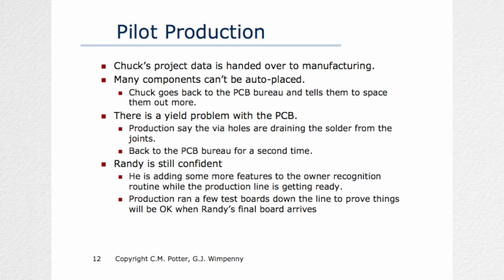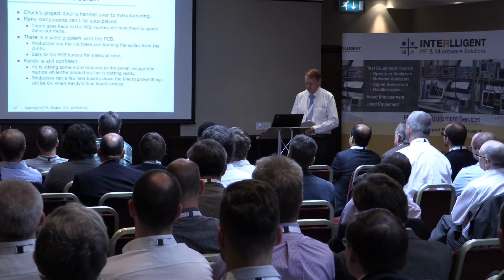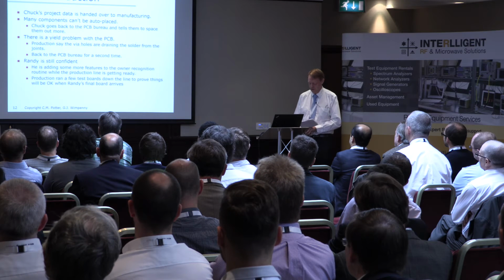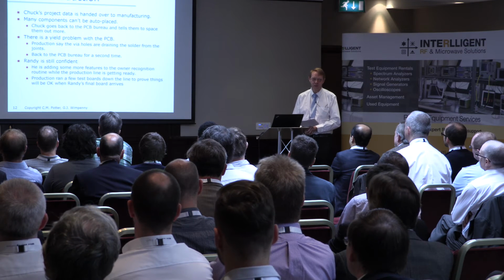So then he finds that there's a yield problem with the PCB, and that's because the holes that he specified are using too small a drill size, for example. And so they need to have bigger drills, bigger pad sizes, spaced out even further, go back again. They say they've never had this trouble before. But anyway, they'll fit in Chuck's rush job now as soon as they can.